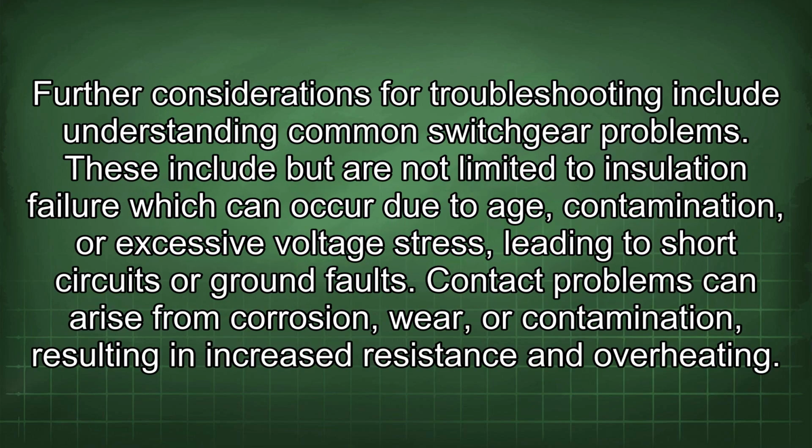Further considerations for troubleshooting include understanding common switchgear problems. These include, but are not limited to, insulation failure, which can occur due to age, contamination, or excessive voltage stress, leading to short circuits or ground faults. Contact problems can arise from corrosion, wear, or contamination, resulting in increased resistance and overheating.